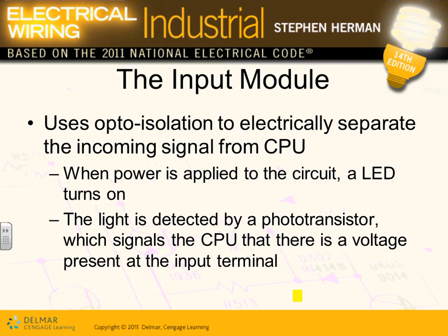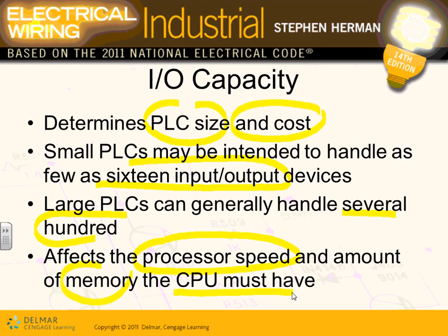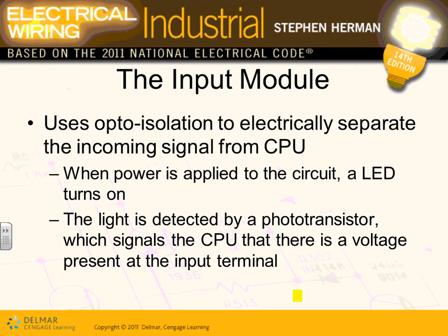Okay, so then we go into the input devices. These are the programming input-output devices. What the input device does, you're going to see, guys, in a second: isolation. Has anybody heard that term? What they do is electrically separate the incoming signal from the CPU. Now you need a signal coming from a sensor. That signal could be corrupted.